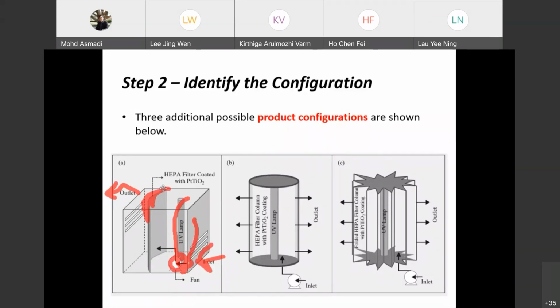This is the catalyst you put here. So the airflow comes in and makes close contact with the catalyst, and then goes outside. Meaning the reaction occurs here. Decomposition occurs here, and then H2O and CO2, HX and so on come out.